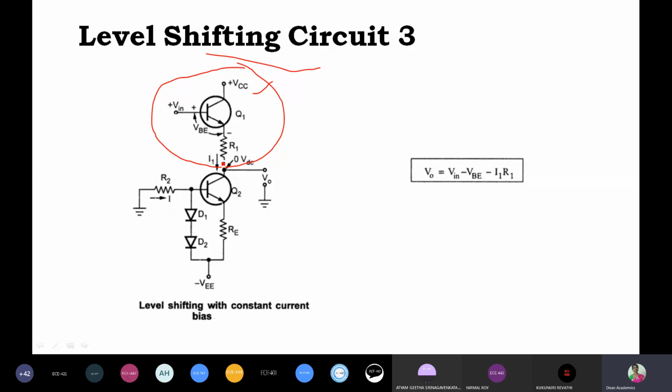After that, below R1 we connected R2. With only R1 we understood there is not much variation in the output. DC voltage earlier if it was 10, now it is becoming 9.3, not much variation. So that arrangement is not that effective.